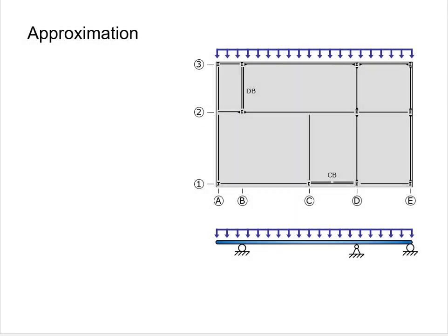If the diaphragm is supported at 3 or more locations in a direction, the equivalent beam model is indeterminate. In later chapters, we will cover how to analyze indeterminate beams, but most of the time we make an approximation to deal with these cases. The approximation we typically make is to treat each panel of the diaphragm as acting independently.